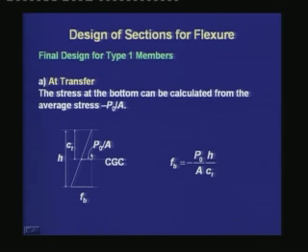See here, we are doing the calculation in a simplified way. Instead of writing the stress in terms of individual components of a uniform stress and a varying stress, we are writing directly using the similarity of triangles concept, since the stress block is triangular. Here we are getting the advantage of a triangular stress block.